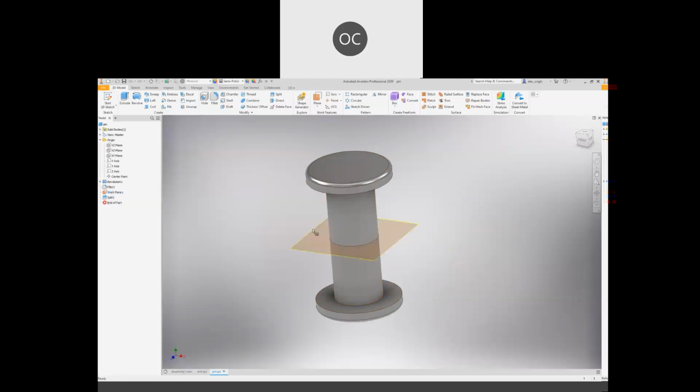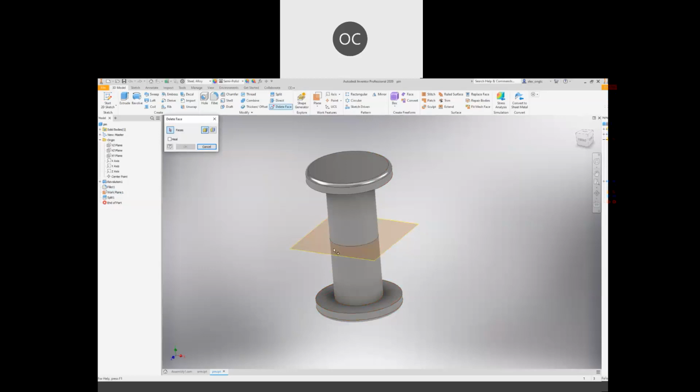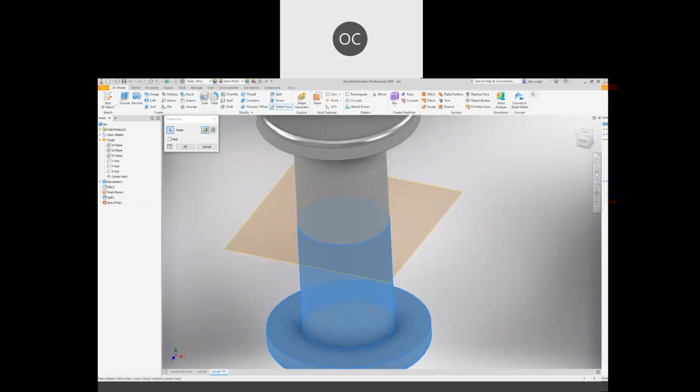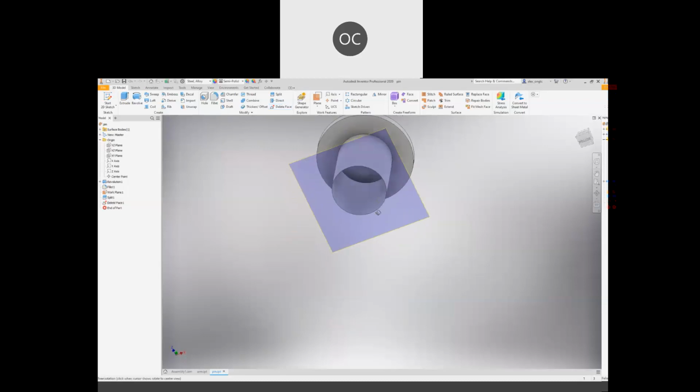So then we want to remove the bottom part or the top part. So you go to delete face here. Delete face. So delete face, you click which one you want to remove. Basically all of it. Just click on the surface here. I click all the ones on the bottom part itself. Select individual, select surface, lump or void. You leave it as the default one, then click OK. So basically we left this part here. Left this part.